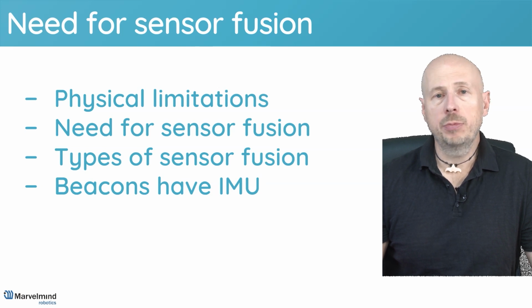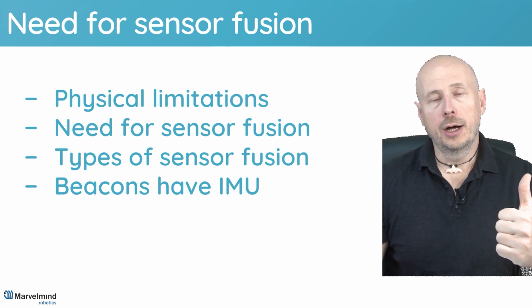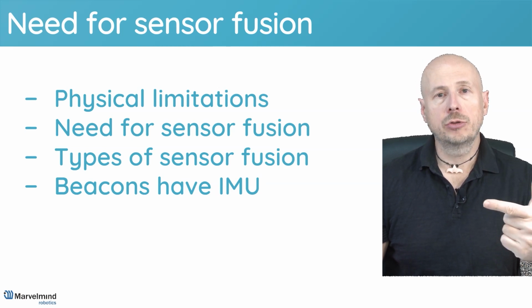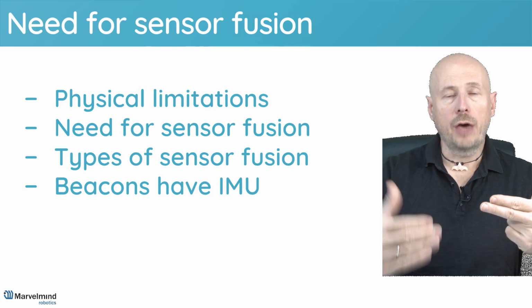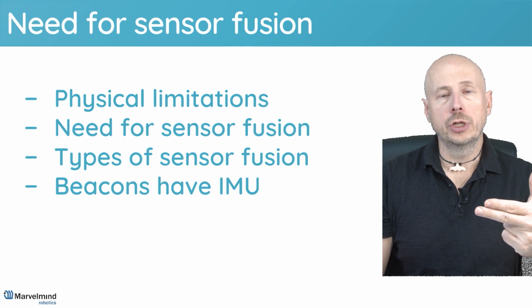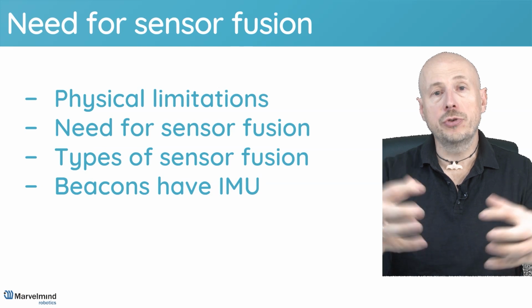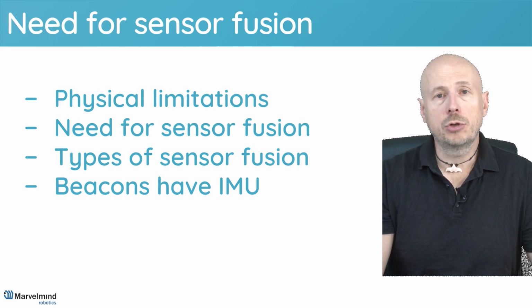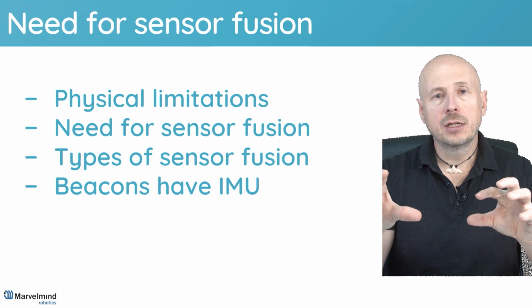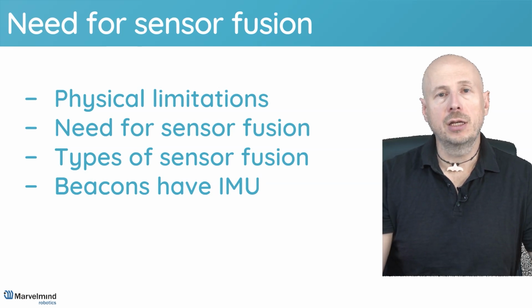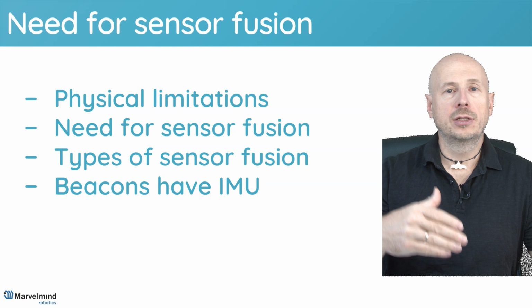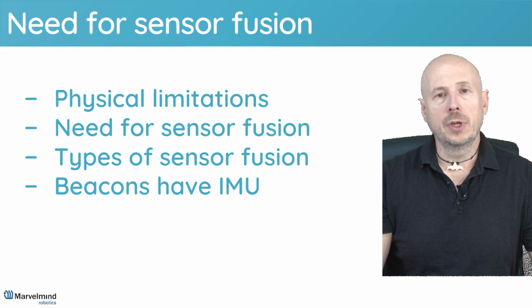Because sensor fusion may be done with many things. For example, in our robots, we do have sensor fusion between odometry, ultrasound, and IMU. We have in our Boxy robot, for example, also Intel RealSense, so a visual positioning system. So it can be sensor fused as well. So this is why it's my favorite topic, because you can achieve the best of the best by smartly, commercially, technically combining all this data together.